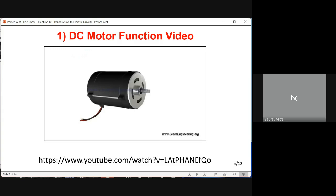The motor has two parts. One is called the armature, which is the rotating part, and the other is called the field, which is the static part. Whenever this current is taken inside the motor, the field coil is receiving supply and generates a magnetomotive force, and the armature coil is also getting supply from the external source, so it is a current carrying conductor. Now you have to apply Fleming's left hand rule, which concerns a current carrying conductor. How is the current carried? Because we connect the electric supply externally to these two points, they take the current inside and give it to the armature. So current carrying conductor means armature conductor.